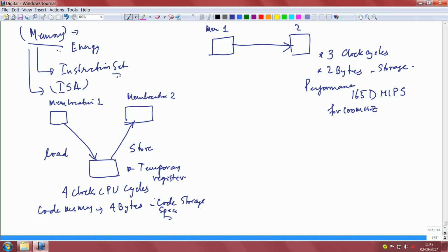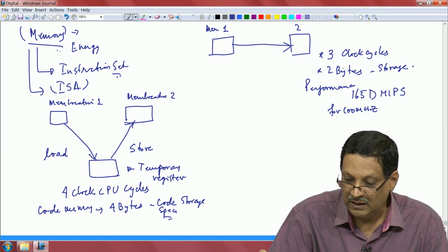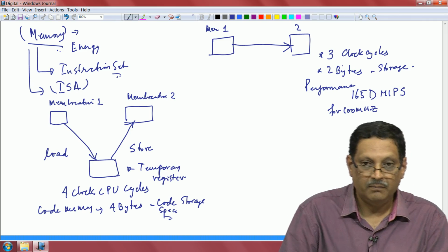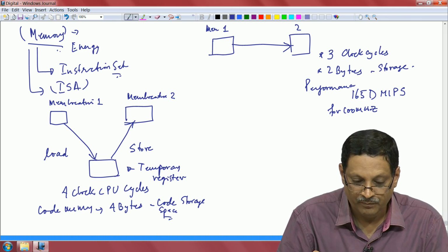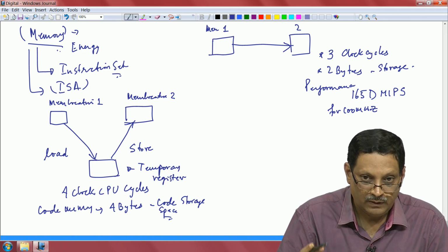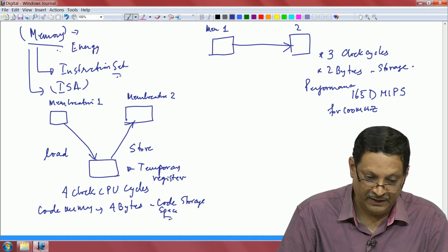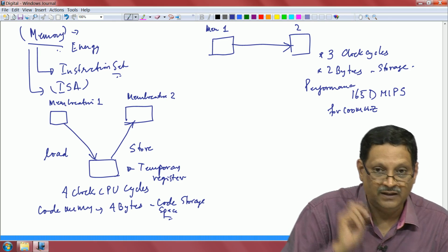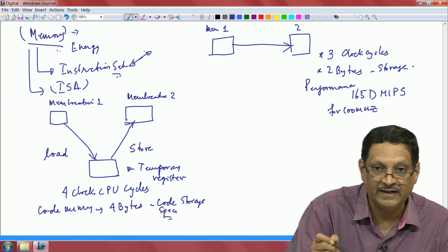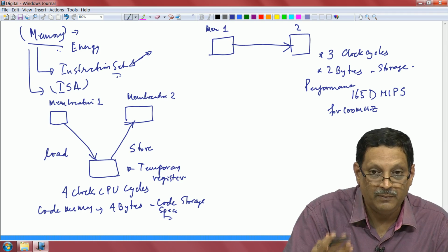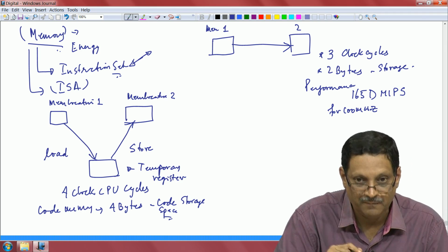You need more program memory, whereas you need less program memory here, and you get better performance, a lower number of CPU clock cycles. So, memory is a very important parameter to be considered when you choose the CPU for your particular application, keeping in mind the instruction set that is associated with the manipulation of these memory locations.